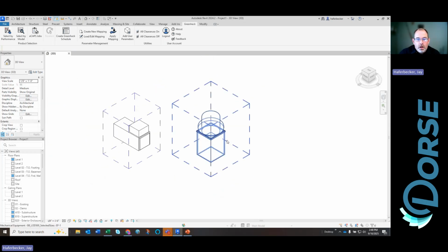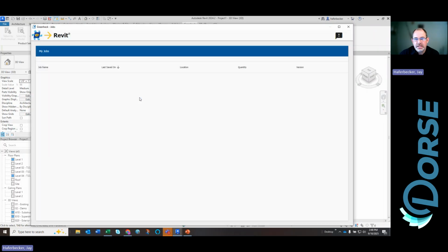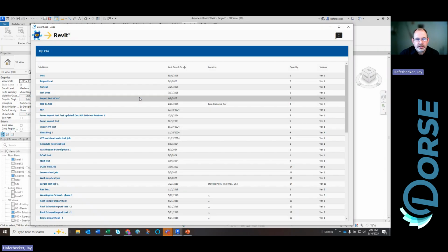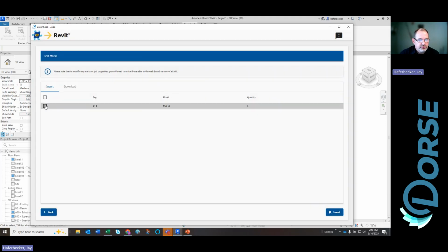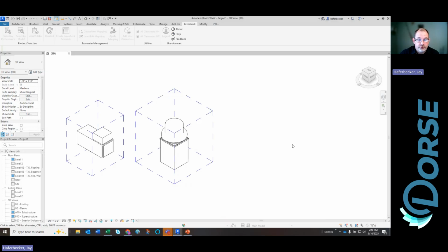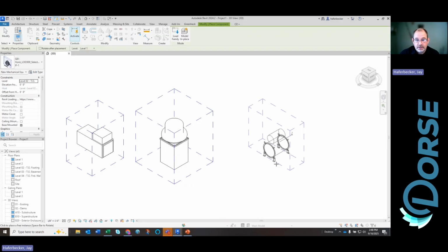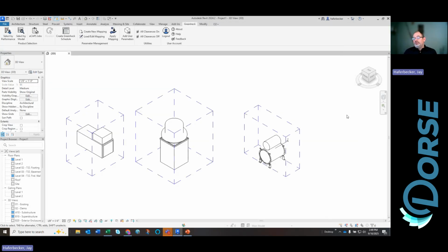Okay. All right, so we talked about two of the three different methods for inserting Revit content. The third method is from a previously created eCAPS job. So if you remember correctly, we created that job called test earlier, and I think that had a little QEI on it, right? So we go ahead and we can insert that Revit content as well from that previously created eCAPS job. And again, it just brings it on my cursor. This is a LOD 300 design, and we place it in a building, and away we go. A couple different workflows there. One workflow is maybe you want to make all your selections first and then draft later, kind of like what we just did here.